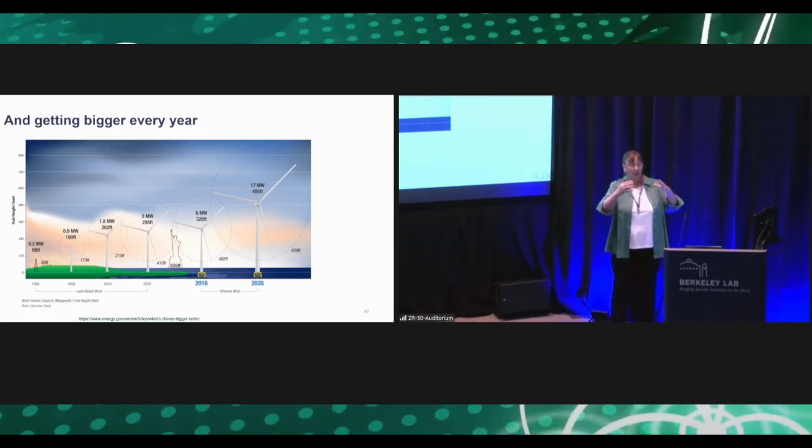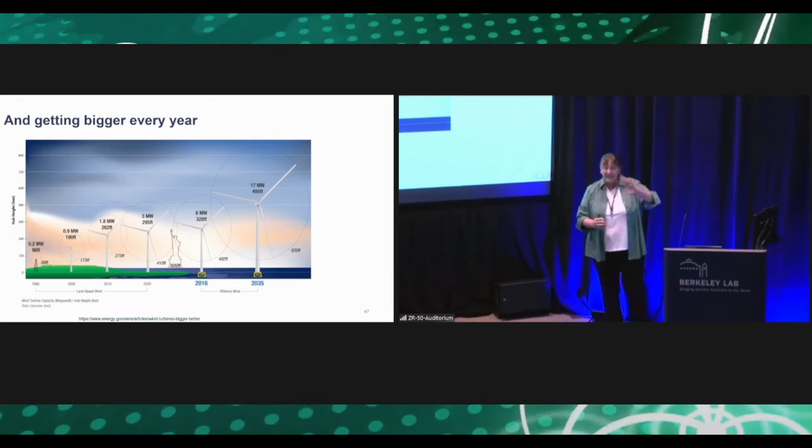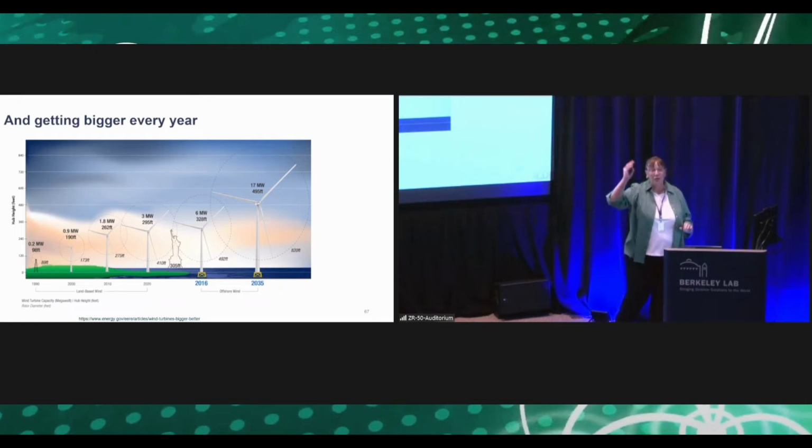If you put a wind turbine very close to the ground, you have a slower wind speed. On average, as you go higher, you get faster winds. With that cube factor, if you double the winds, you've got 8 times the power output. So we want to maximize the output per turbine, and one way of doing it is making them bigger and taller. Hopefully I've convinced you this is kind of a big problem.